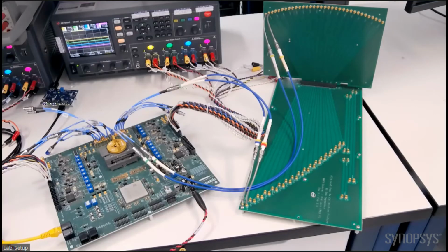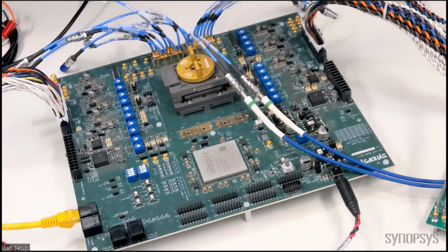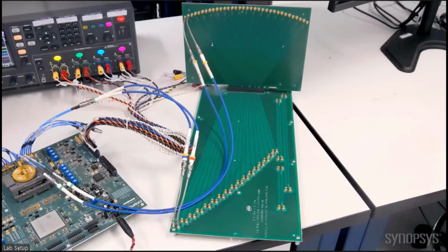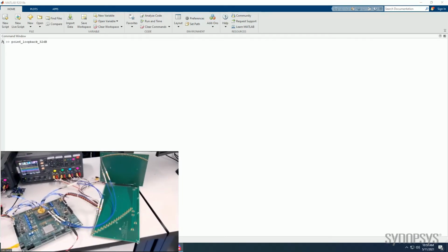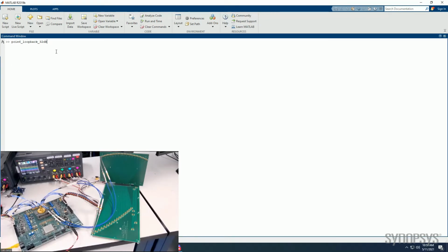The next setup demonstrates the PHY in loopback over a PCIe Gen 5 compliance-based board channel. For this test, we are choosing a channel with total loss of 32 dB to match the PCIe Gen 6 standard maximum loss guidelines for receiver testing. This channel includes reflection, non-linearity, and discontinuities, which makes it a more difficult channel compared to a higher loss channel, which is linear in nature. This part is brought out of reset and initialized into 64 Gbps PAM4 loopback.